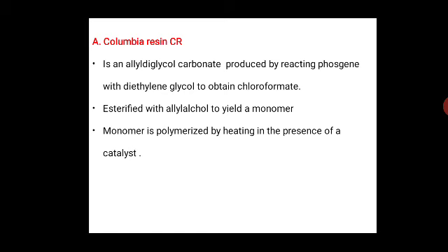The casting operation is performed in such a manner that the final product in sheet form has surfaces of optical quality. The predominant advantage of this material, CR39, is that it is available in large sheets of 48 to 60 inches in a number of different thicknesses, with a surface finish which is nearly optically perfect. So the material is widely applicable for many photoelasticity applications.